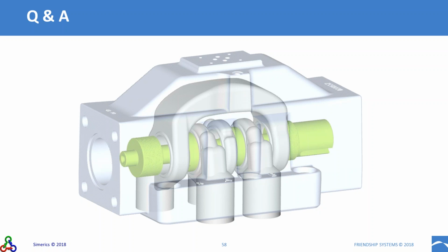In this case, we just need a single objective method, because we have only one objective, which is the flow rate. And we selected that method because we want to run only a local optimization in the vicinity of the best design from the DOE. We have good experiences with that method, and it's one of the methods we suggest for this kind of application, local single objective optimization, because it's pretty robust and also efficient.